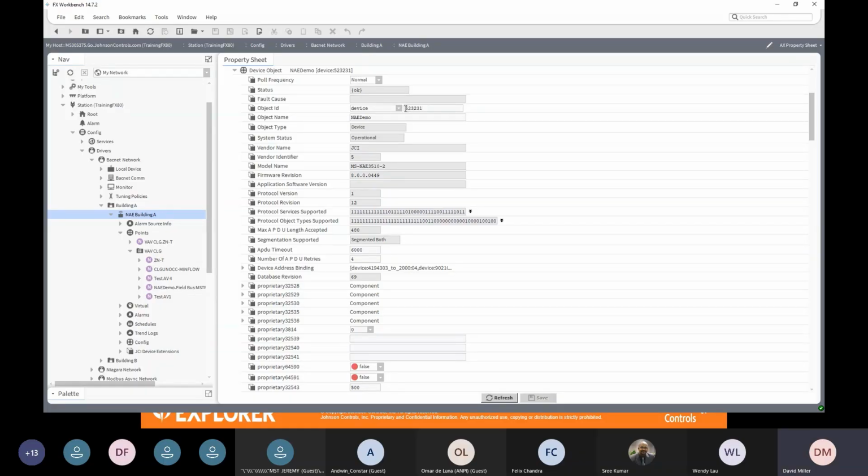Okay. Now that number needs to be unique across the entire site. In the Metasys world, those numbers are typically set automatically to make sure that they're unique. But when you have a system where it's multi-vendor, where lots of different suppliers are providing controllers, the device ID number can be anything, but it typically has to be set in the device.